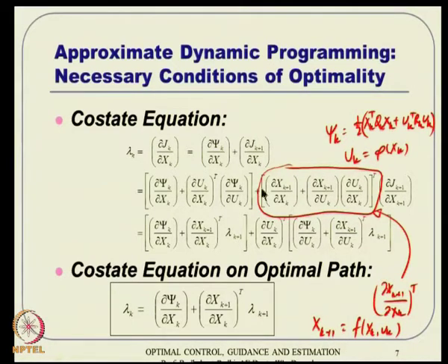So, because of that this is non-zero, that means this one comes directly from xk plus 1 perturbation. So, I write it as something like this term, del xk plus 1 by del xk transpose times this one. But this particular one you can realize that xk plus 1 is a function of both xk and uk, and uk is a function of xk again. Okay. So, this particular term is because of that: first is directly, then the second one is through uk.